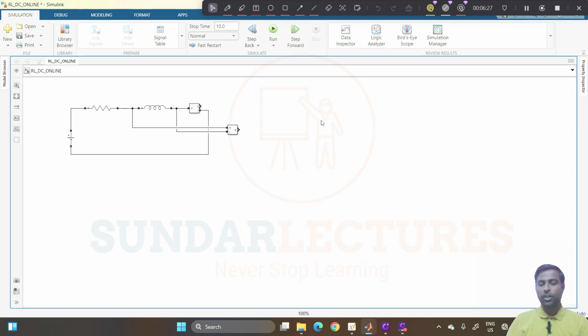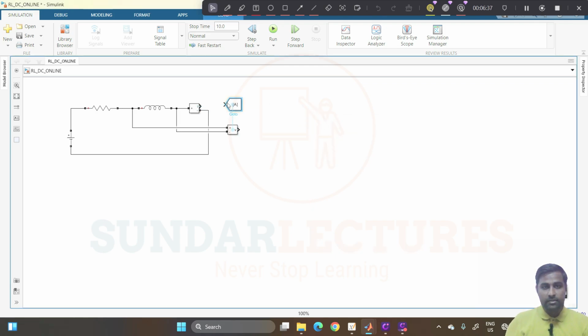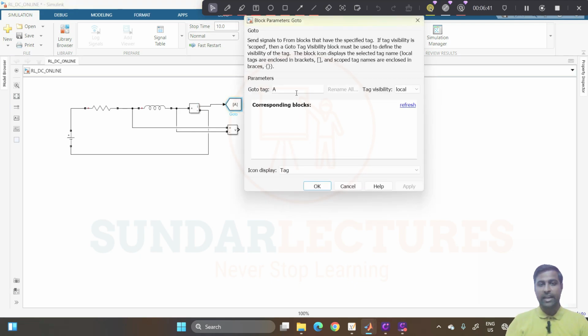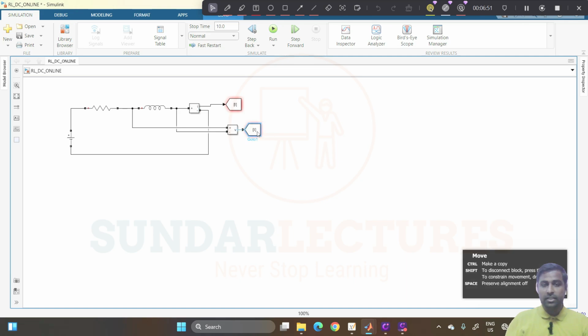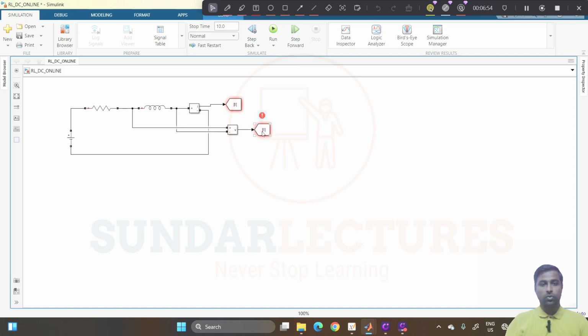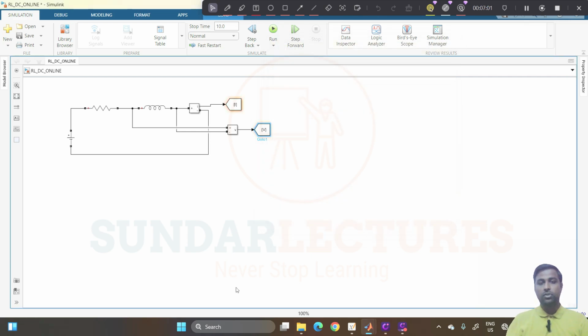So again, what you need to do is get a block, you just get this block and connect this one. So this value will be current, right? So you just make it the tag I, and then again you copy this, paste it out, and connect these two. You go here and change this tag to V, because there should not be the same tags. So this is V, right?